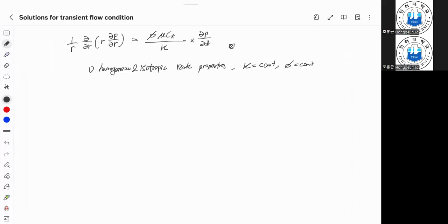And the second assumption that we need for the equation up to here is that we assume radial flow, and this radial flow goes all the way up through the entire formation thickness. So basically, we assume the reservoir goes by this shape, and we have a well in the center, and the pressure diffuses in a radial direction. So fluid goes in a radial direction.